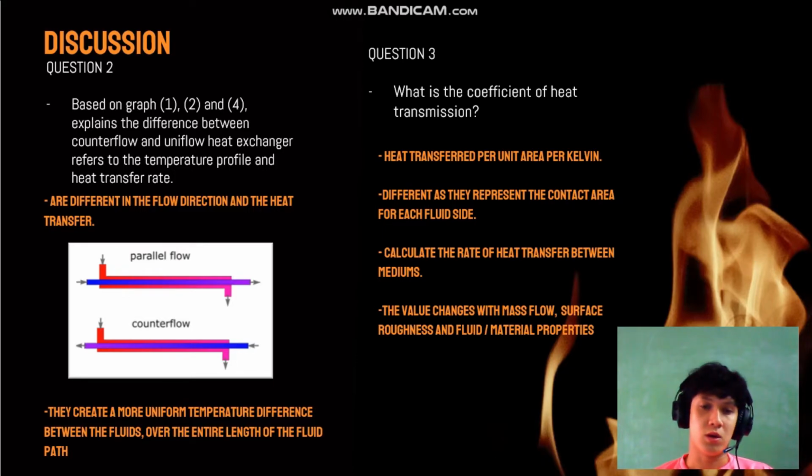Counterflow, hot and cold fluid flow in opposite directions. Counterflow gives higher efficiency and heat transfer in a heat exchanger because it creates a more uniform temperature difference between the fluids over the entire length of the fluid path. Basically, the cold water escapes the heat exchanger quicker compared to parallel flow.